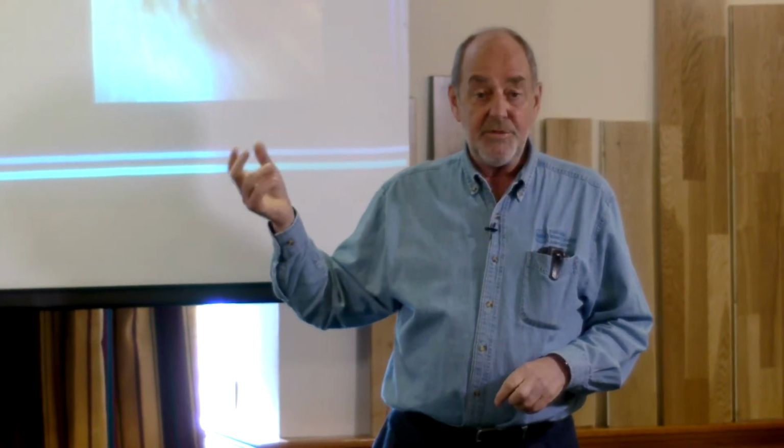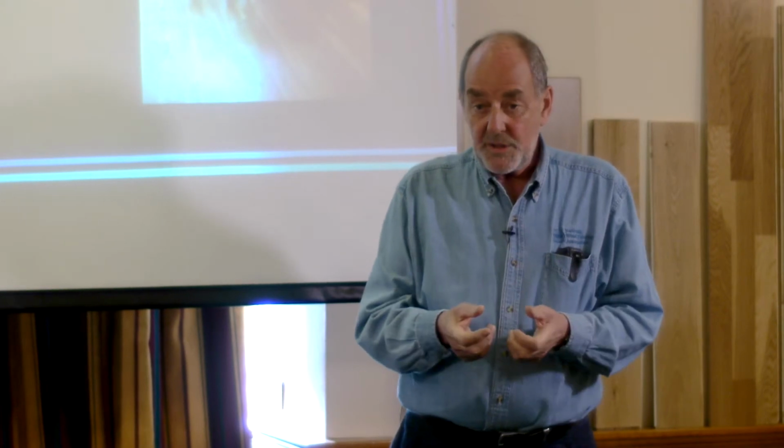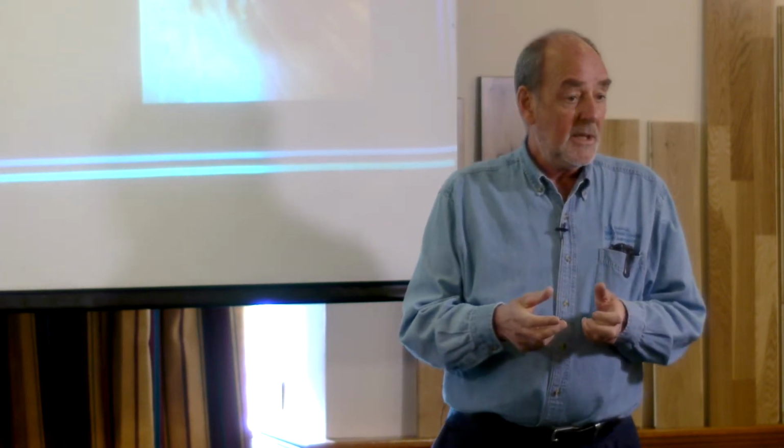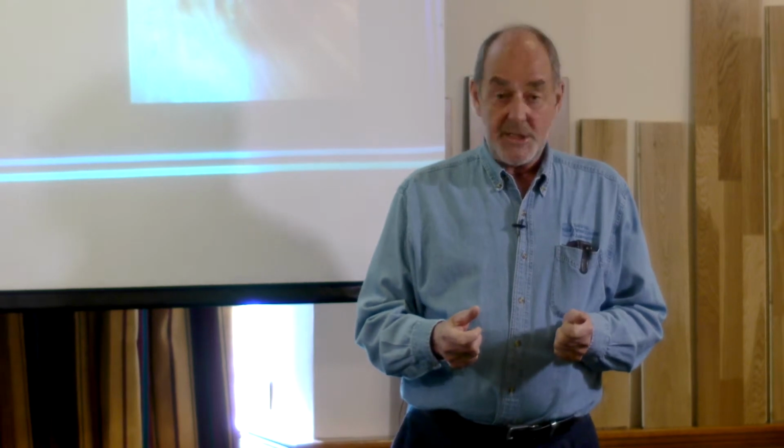Most of the problems with wood floors are because of moisture. 90%, in my experience, of the problems with wood floors are about expansion and contraction. And it's solid floors that do that. You save yourself an awful lot of bother by just staying away from solid.